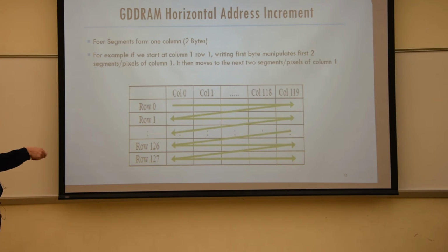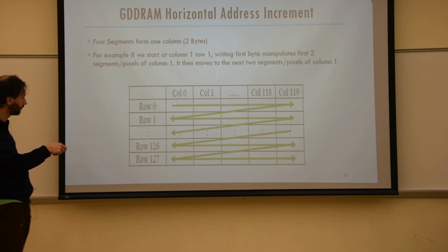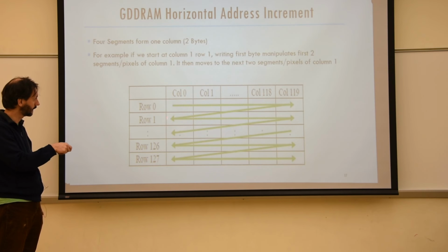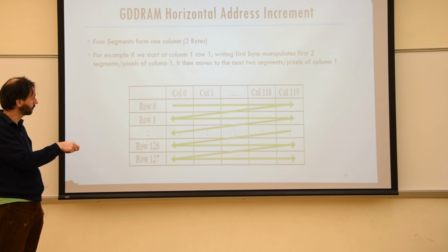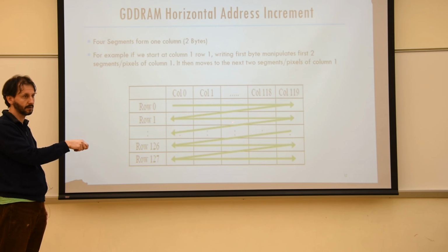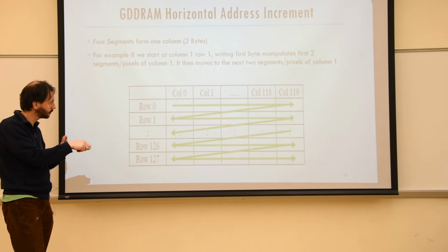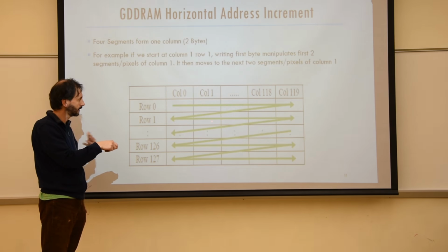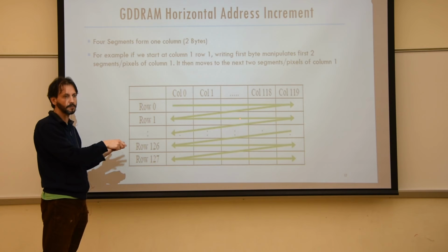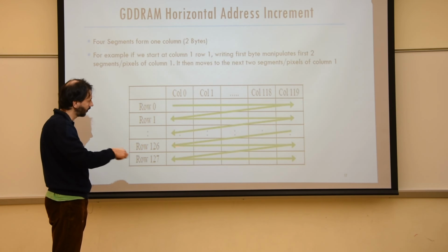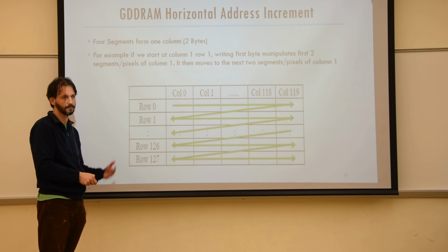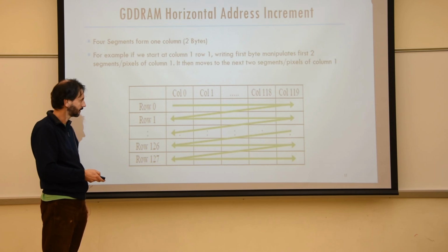Alright, so how does the OLED react? Well, if you are writing, say, a particular column 1, row 1, for example, over here, then once that is finished, the OLED expects you to write the next cell over here. So you do not have to tell it a different location. By default, it will move to the next cell. And that helps, of course, because then you can go through this whole display and write pixel after pixel. You can write anything you would like to see.